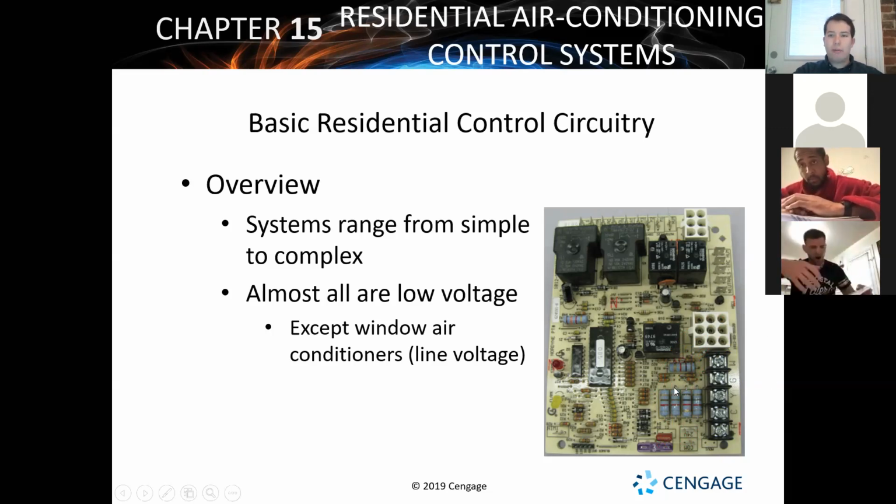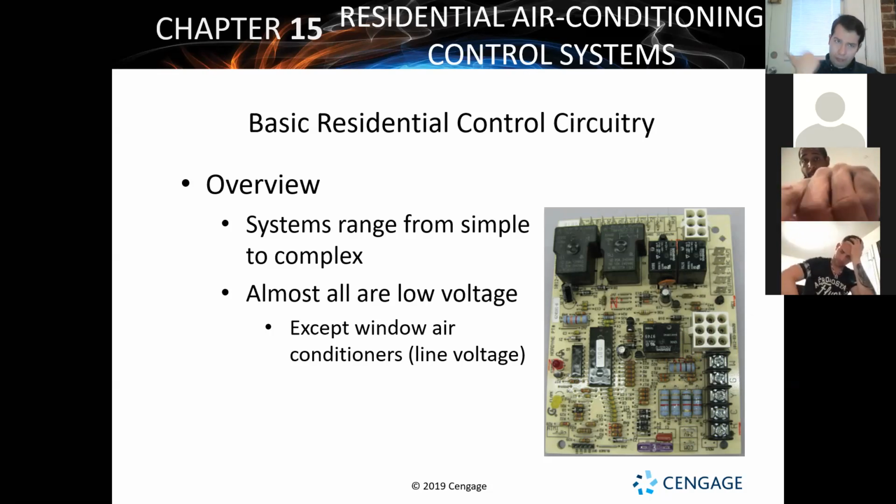So you'll have, you can see there's these large plugs that will usually be for switches and controls. So your pressure switches, your temperature switches, basically any sort of safety to make sure the system doesn't come on or turn off, or does turn off if an unsafe situation arises, whether that's overheating, overpressurizing, whatever it might be. That stuff is all fed back to the board there.